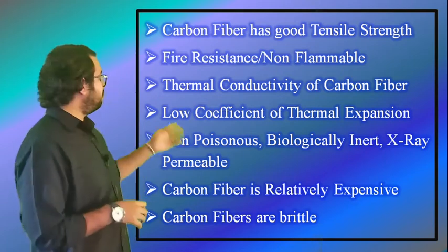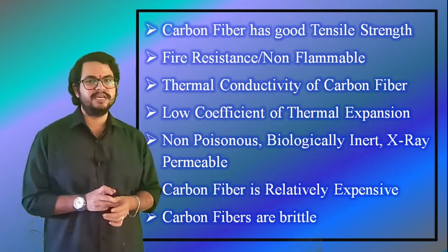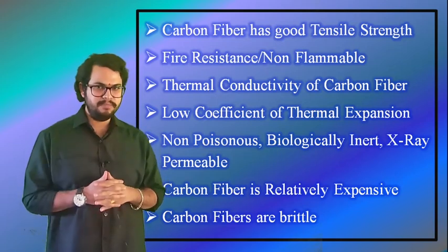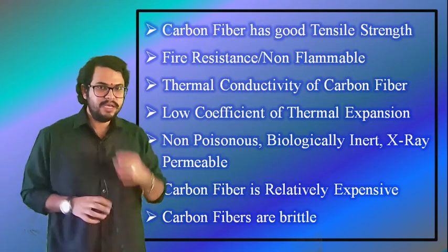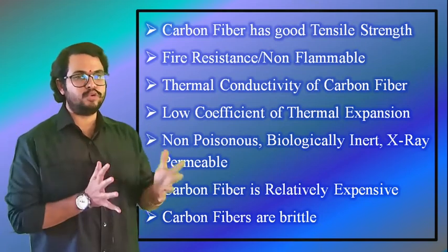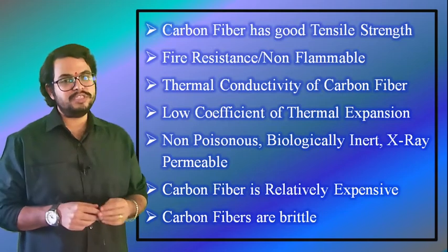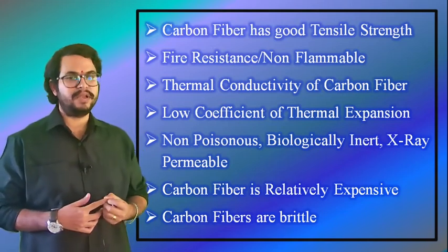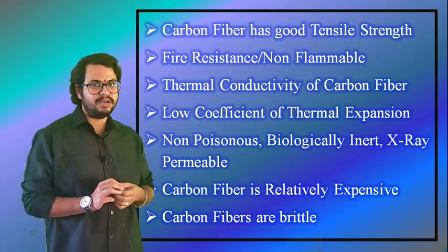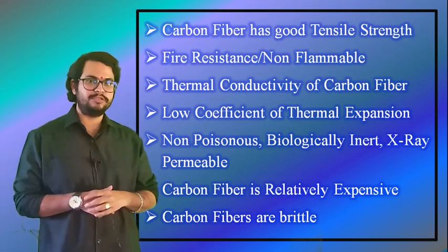Next, the thermal conductivity of carbon fiber. Thermal conductivity is the quantity of heat transmitted through a unit thickness in a direction normal to a surface of unit area because of a unit temperature gradient under steady conditions. In other words, it's a measure of how easily heat flows through a material. Because there are many variations on the theme of carbon fiber, it is not possible to pinpoint exactly the thermal conductivity. Special types of carbon fiber have been specifically designed for high or low thermal conductivities. There are also efforts to enhance this feature.